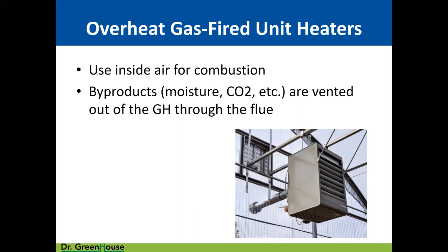I mentioned already we can use overhead gas-fired unit heaters and use that inside air for combustion as opposed to bringing in outside air for combustion, and then relieving that water vapor and the other byproducts to the outside through a flue. And then we would infiltrate, and what would happen is that air that was used for combustion would then suck some air also from the outside through infiltration, which we would hope would be drier than what's inside. And that's partly why we would need the heating, especially if it was 20 degrees outside.